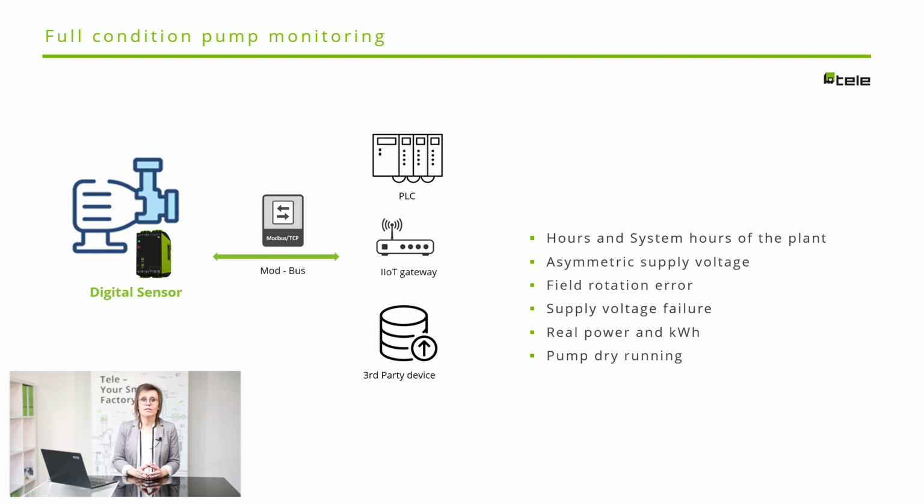Monitoring relays can be dispensed with. The digital sensor includes features which prevent the load being affected by anomalies on the supply lines. Local alarms can be used to disable the plant, prevent the pump from starting and switch off independently from the cloud communication in case of a motor load alarm.